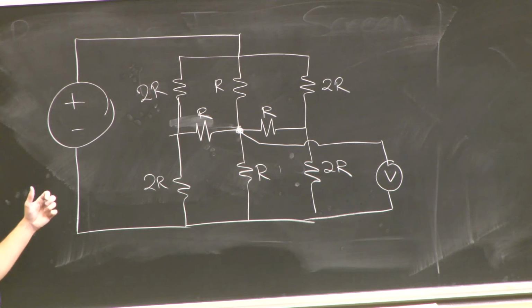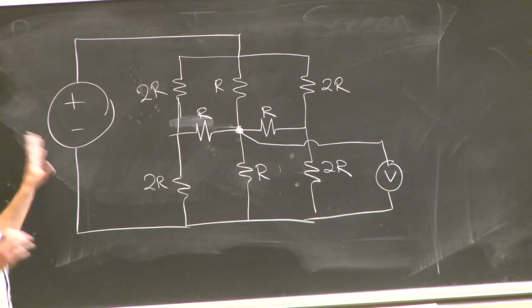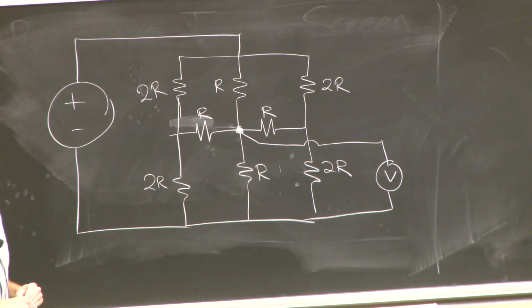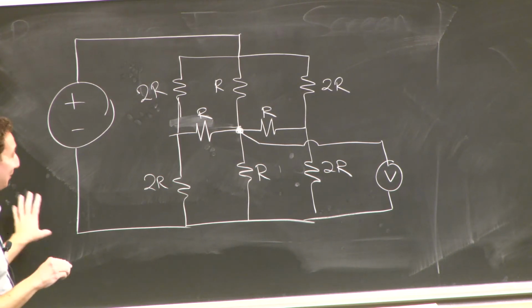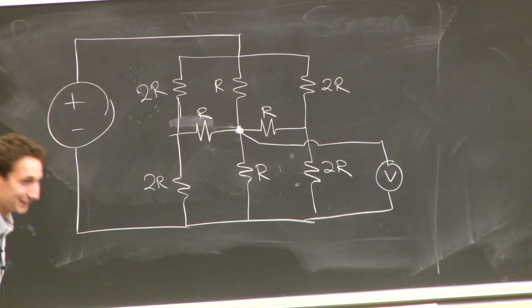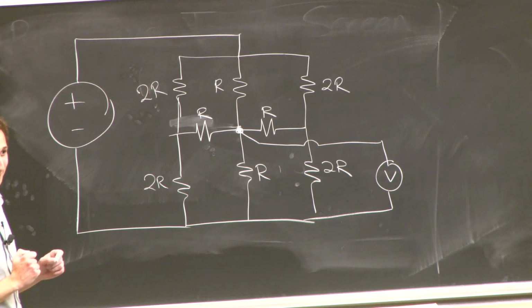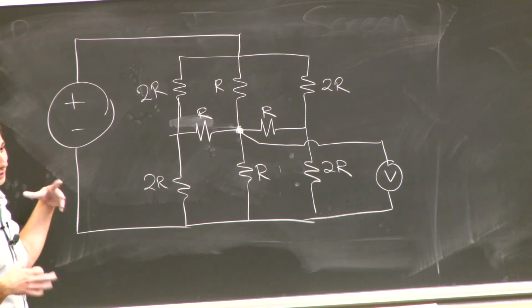There's nothing left, yeah. Oh yeah, let's do nodal analysis. Let's not. There's so many nodes in this circuit, right? This is a hopeless number of nodes. Not hopeless, but okay, never hopeless. You can always do nodal analysis, yeah. You have a symmetry between all the two R's and the R's. What if you can somehow fold it four ways so you get one box of just 2R, R, and R? So I have some level of symmetry in my circuit, right? And the suggestion is, can you collapse the four R's?